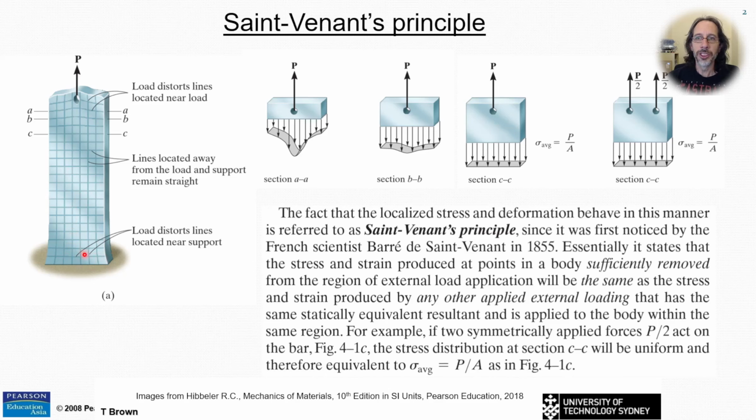So the obvious question is, how far away do you need to be? Typically, if you're one width away from where the loading is, not the thickness, but one width, then the variation in stress is less than 10% from the average stress.